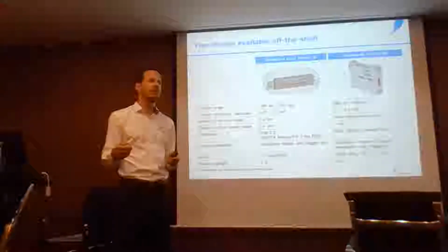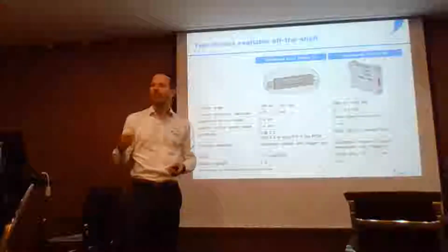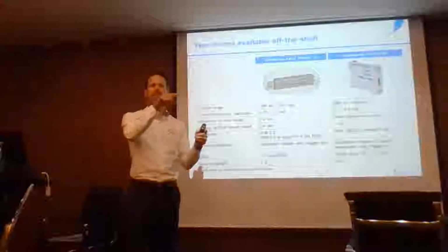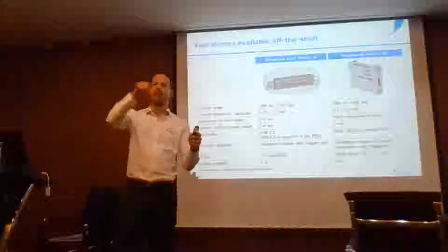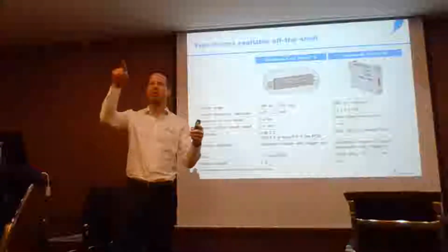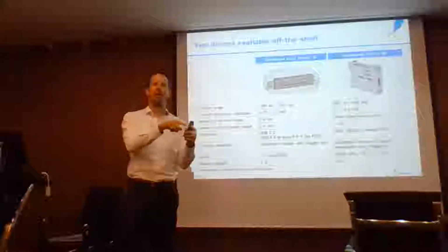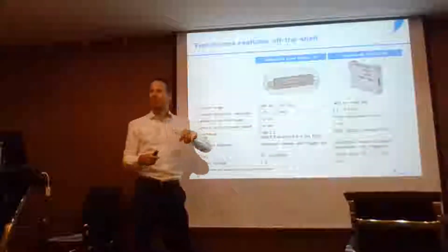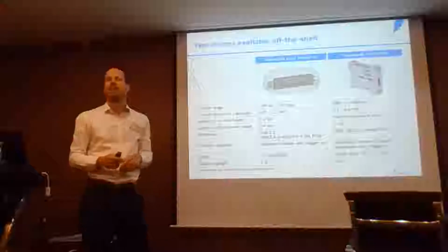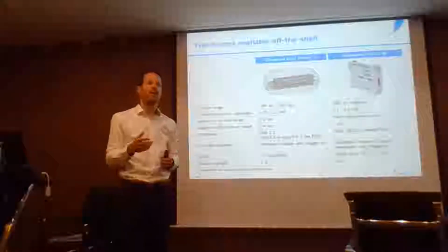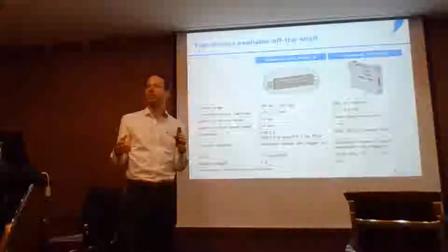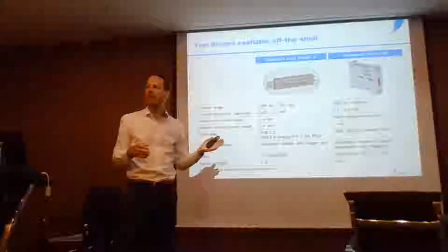But you can also use the analog input as a trigger. For example, you can program a waveform, like maybe a step function, or a triangle, or a sawtooth wave. And then that waveform can be triggered each time the analog input gets a trigger signal. That's how you can synchronize our lens with a camera or with some other light for image stacking.